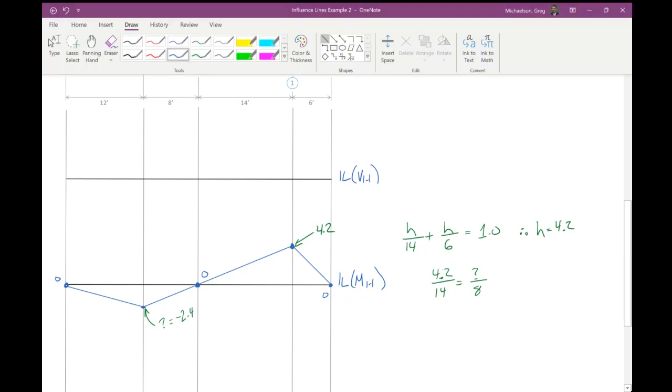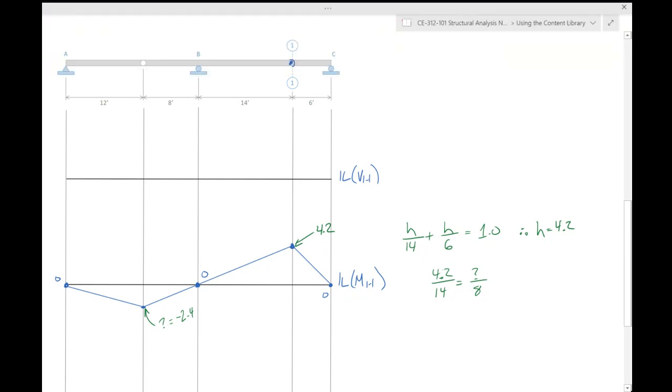I know we're running out of time, so I'll do this one quick. How do we do it with the shear? We institute a shear release. Left side goes down, right side goes up. Has to be anchored at 0. And again, just like Mr. Enoch mentioned, 3 rigid segments. So what does our influence line look like?